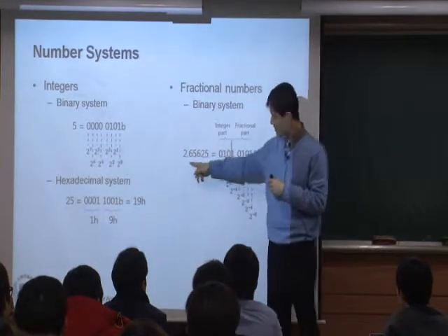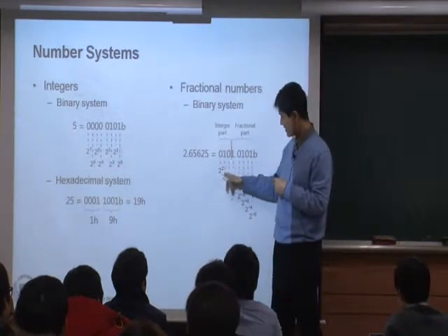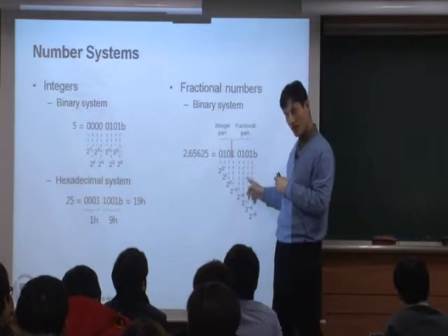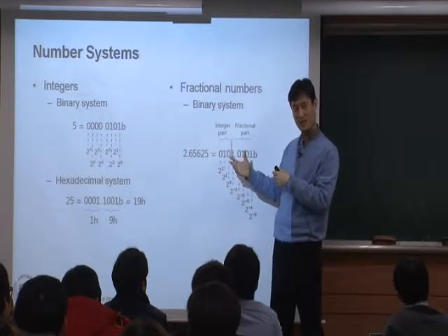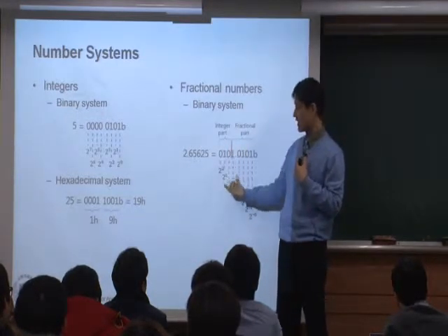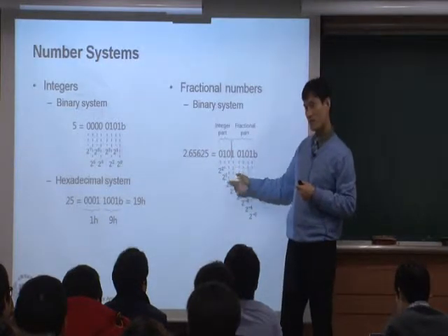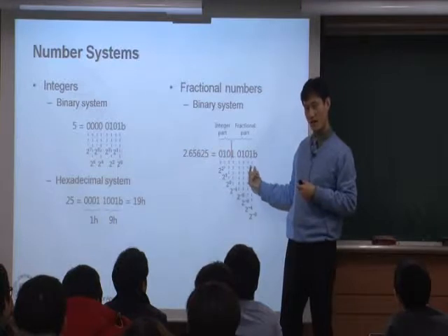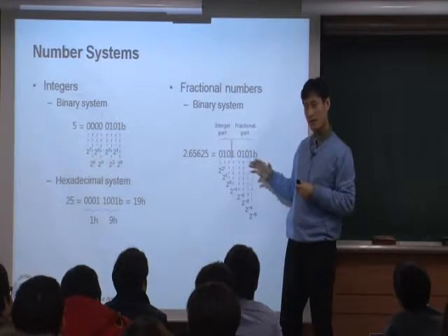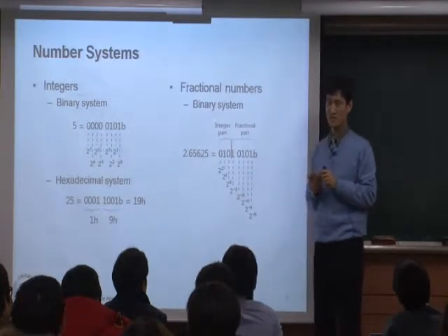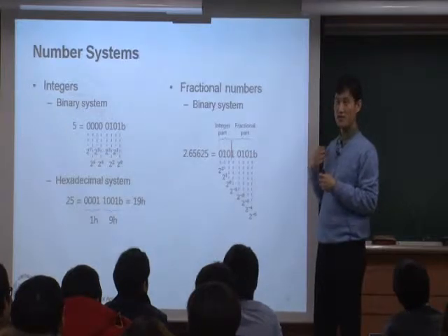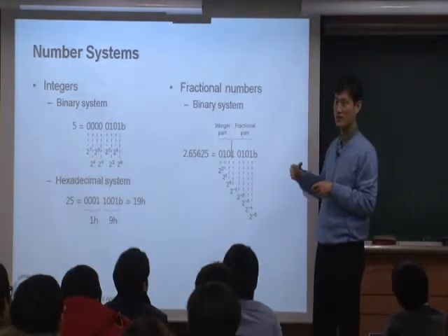It can be 64 plus 16 plus 4 plus 1, or it can be some other number. If we want to read that as a hexadecimal integer, then this is going to be 55H. The microprocessor doesn't know anything about those. It's for us. We decide how to read this.